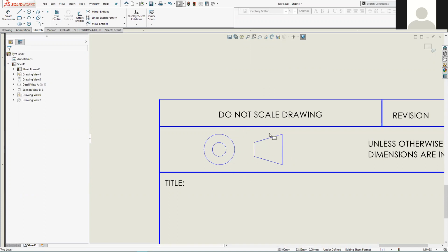So again, there's a logical order that you want to create these. You want to do the center mark first. The reason I say that is, as we create the center mark, we'll create a point at the center of these two circles. And what the system will then allow us to do is, as we're drawing the center line here, it will align the vertical position of that so that it's horizontal with that point there. So it will ensure that they're both aligned with each other again.